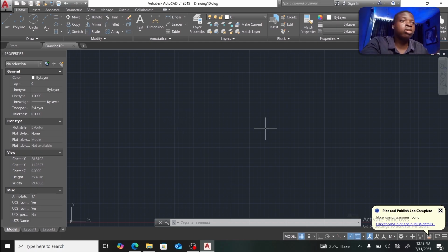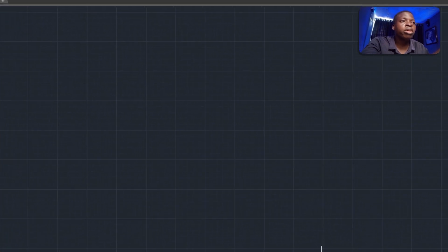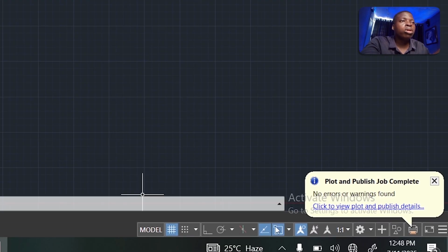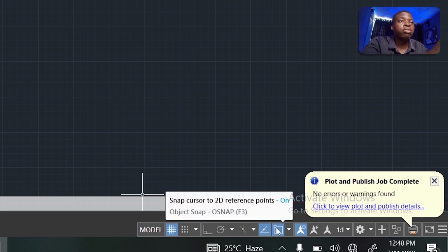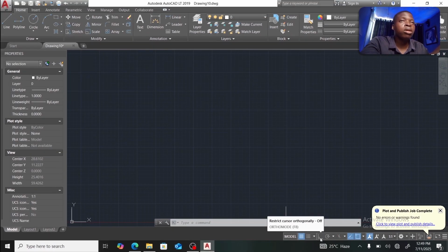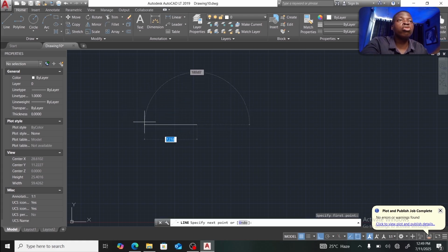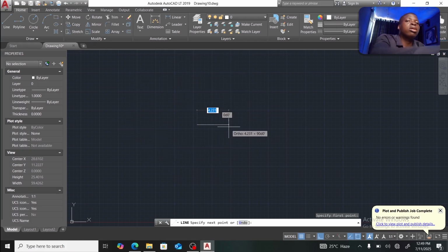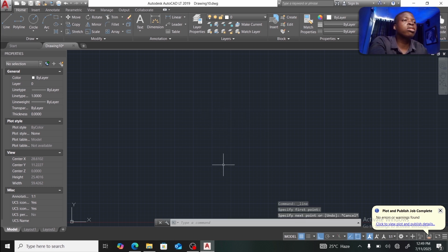But before we start plotting, I also need to introduce us to this little panel at the bottom right here. There are 2 important commands here for us, which are the snap tool, and then the orthogonal. We use it a lot in surveying. The orthogonal is going to change your orientation for your drawing to 90 degrees. So your movement will be restricted to 90 degrees, as you can see. To turn off the tool, press escape.